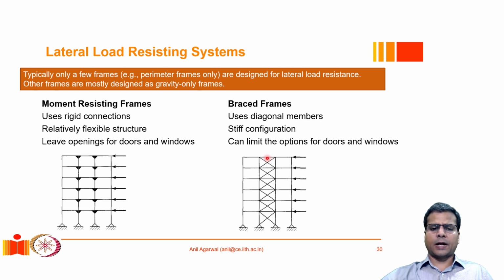There can be another variety wherein you may have a single brace on each side and two bays may be covered. This is kind of an X bracing. For most of the lateral load resisting applications, we avoid any K type of bracing, wherein the braces meet in the middle of the column. It is okay to meet at the middle of the beam, because the beam is not such a critical member for the overall stability of the structure, but having braces meeting at the middle of the column is strictly prohibited under earthquake loading conditions.